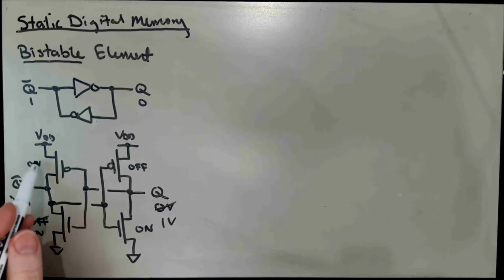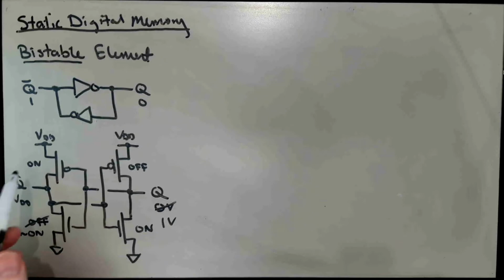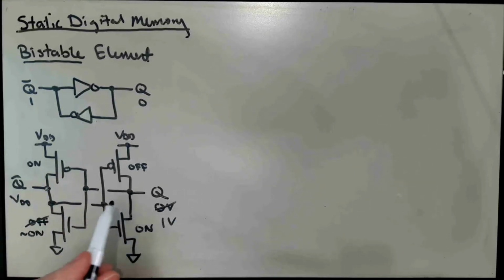And so this thing is blasting out, let's say, hundreds of microamps of current, and this thing is maybe capable of sinking 20 microamps of current or something of that nature with a volt on the gate or so. And so still, this inverter is going to be strongly pulling Q bar up to VDD, and that results in this transistor still being off and this one being on.